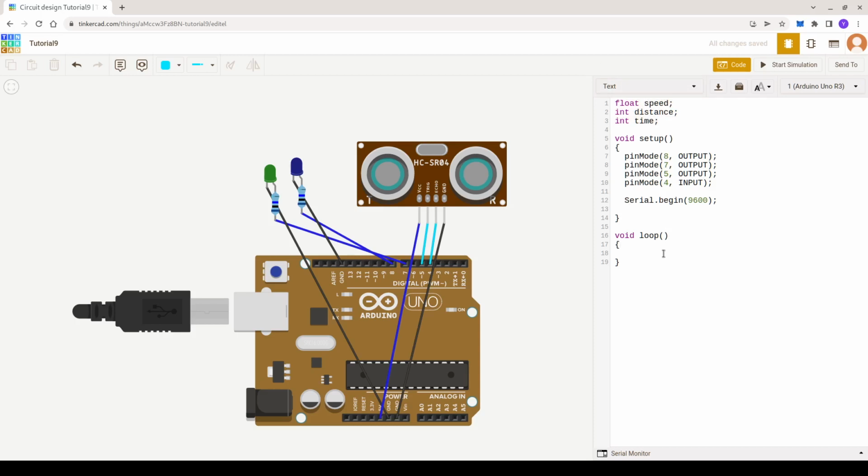Now there is a new function for you guys in this video: delay. And what does this do? As the name suggests, it will just delay the work for something. The value which we are giving in is milliseconds. So if we give 1000, that means 1 second. Okay, guys. And if you want to check this out, let me just show you.